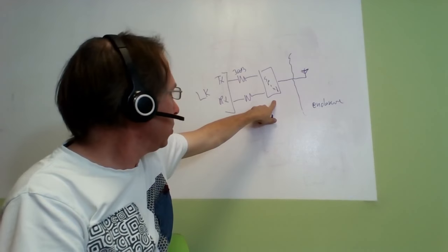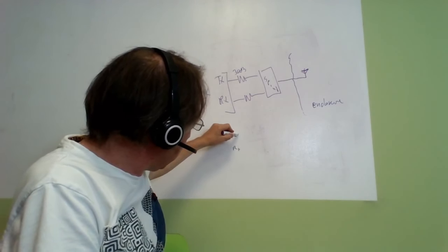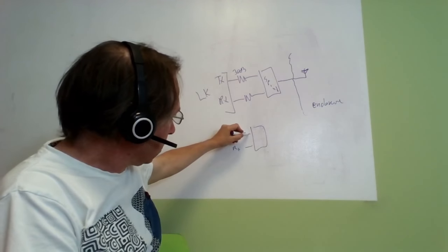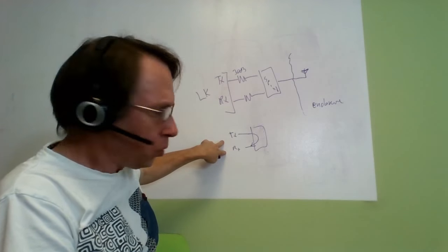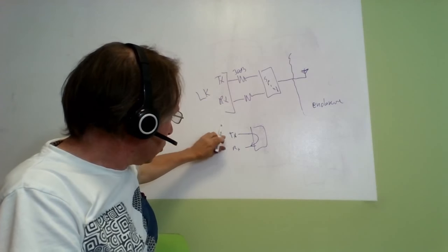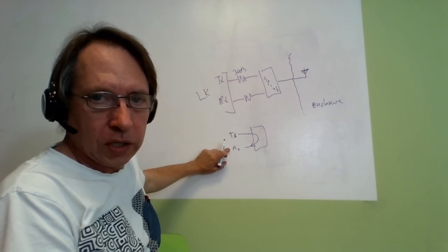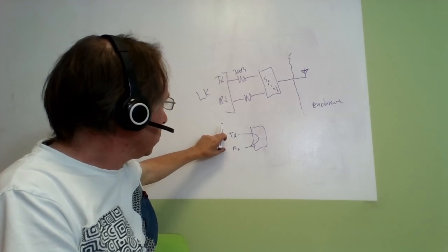And the reason for that is because if you just take the TX and the RX and send them straight into a splitter like this, a lot of times the splitter may not have enough isolation. And what ends up happening is that the transmit power leaks back into the receiver and desenses the receiver. You're basically jamming yourself. So there's two solutions to this. Well, there are three solutions to this.